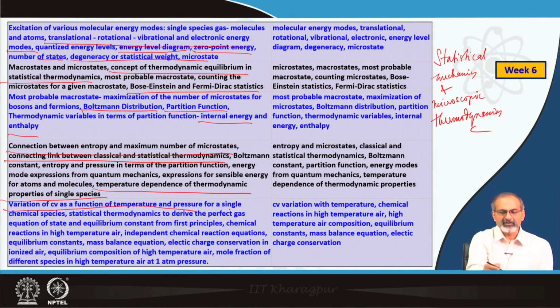Variation of CV as a function of temperature and pressure for a single chemical species, and chemical reactions in high temperature air, the independent chemical reaction equations, how we choose them, the mass balance equation, the electric charge conservation in ionized air, equilibrium composition of high temperature air, mole fraction of different species in high temperature air at 1 atmospheric pressure. Such very interesting, perhaps new concepts for many of you were introduced in this week.